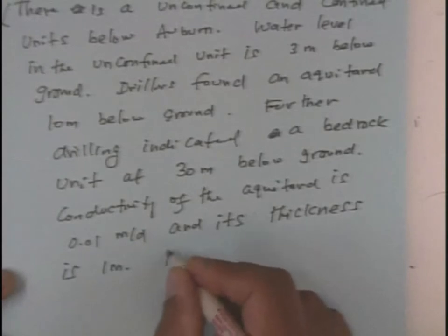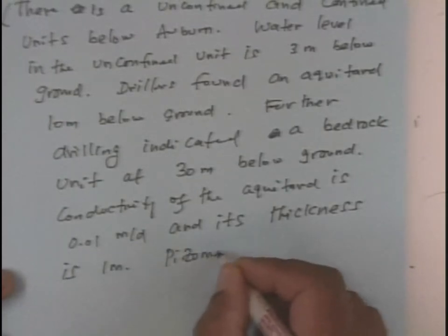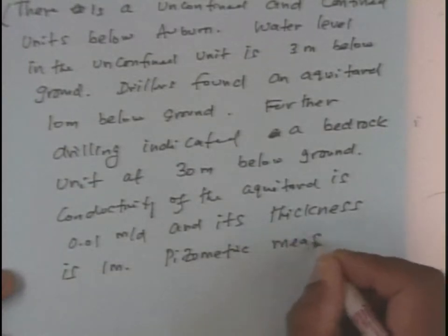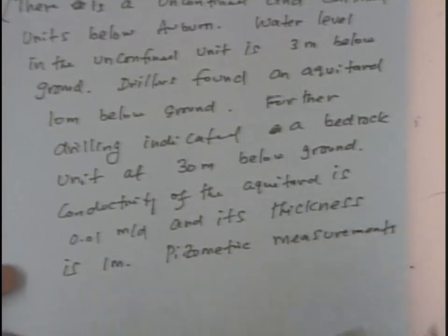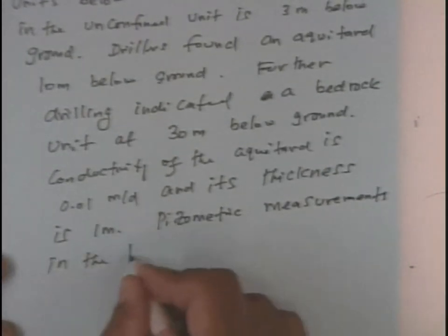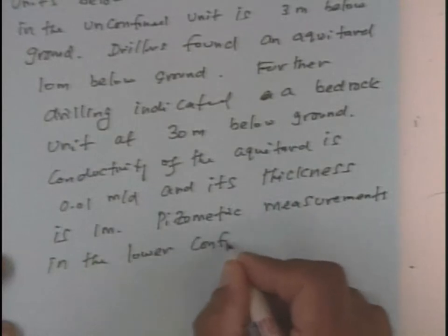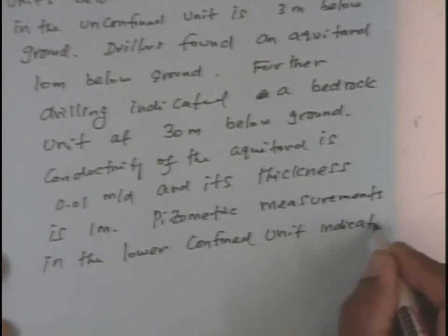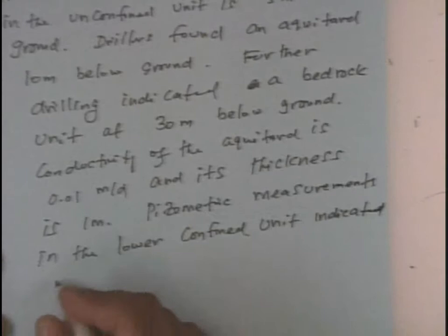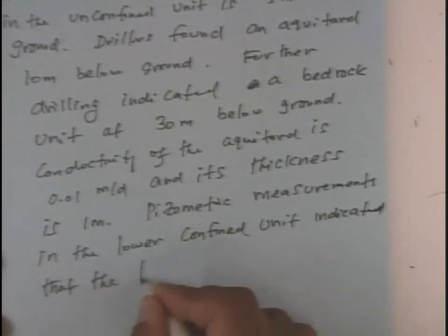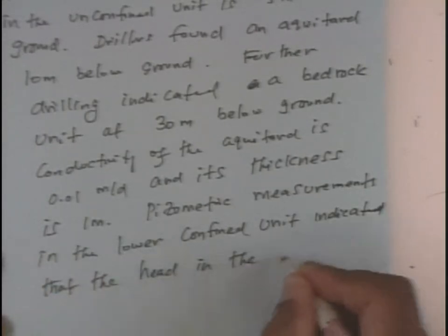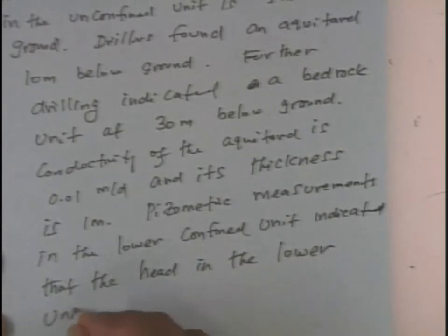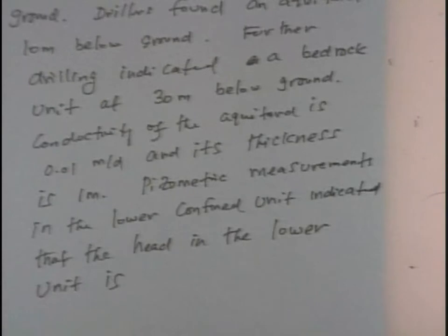Okay. And piezometer measurements in the lower confined unit indicated the head in the lower unit is, let's say, 30 meters.